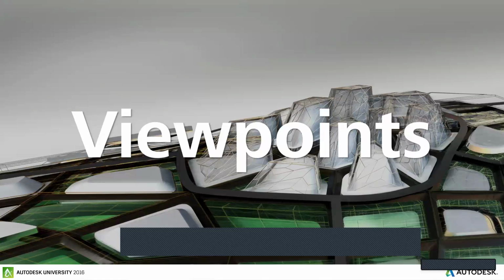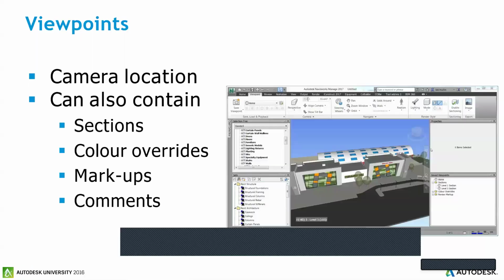Viewpoint is something which is used for the review process. So if you are moving through or walking through the entire building and you find there is some mistake, or you have reviewed it using the review tools, and for example you just measured whether the car parking head height is more or less than 2.75. If you found it to be 1.8, 1.5, something like that, you will mark it there via a cloud that this is wrong and this needs to be updated within our model, right? So for that particular thing, we are going to create a viewpoint. Once anyone opens the file from his own end, it will directly have a viewpoint within. So he will go directly to the viewpoint and check whether someone has marked something, likewise. So that is the entire purpose of working with viewpoints, setting up the cameras and overrides sections.